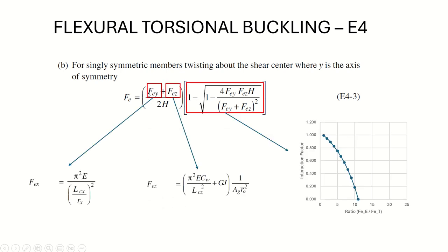If we review what these factors mean, the first one is just elastic buckling, the second one is just the torsion component, and then we have an interaction factor, which is this whole value here. It's represented by this curve, which takes values between 0 and 1, and its function is to compensate the distance between these values, because the code uses a conservative value for the design, not just the average between these two components.